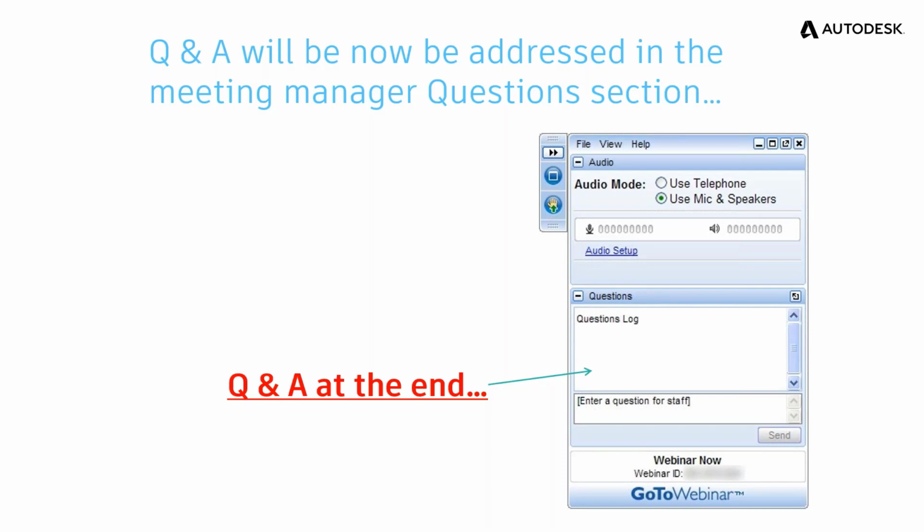I've used them for data extractions. I've also used them with AutoLisp to create bill of materials from it. So it's possible, but as far as if you mean the actual bill of material itself, probably not going to be very useful for that unless you're just making it stretch the number of columns and rows.